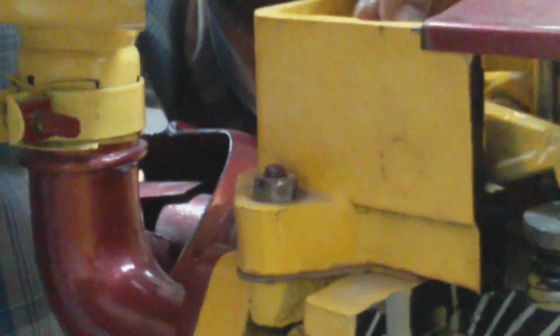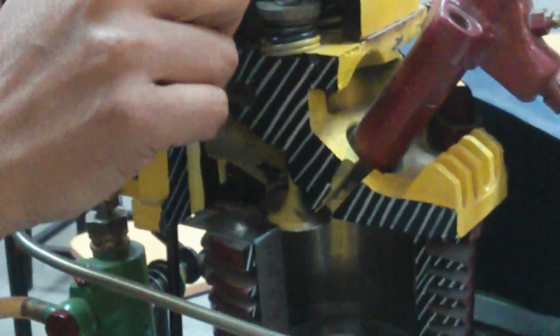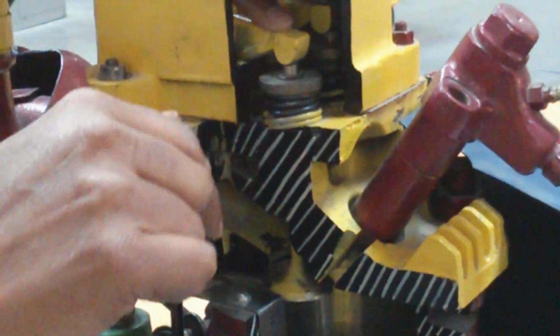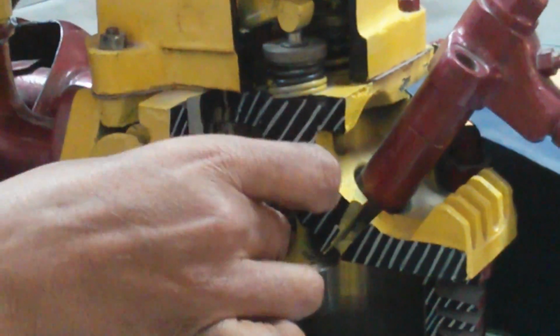From the camshaft I have this, which is called the push rod, and on top of the push rod I have the rocker arms. As the camshaft rotates, the push rod moves upwards, and the upward movement of the push rod causes the rocker arm to move downwards, which pushes the valve tappet and the springs over there. So this end of the rocker arm pushes the spring downwards and the valve is getting opened, right?